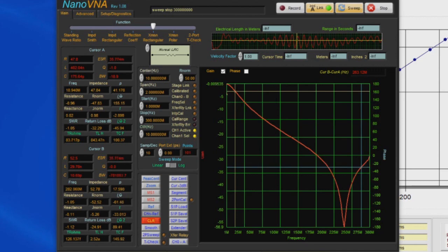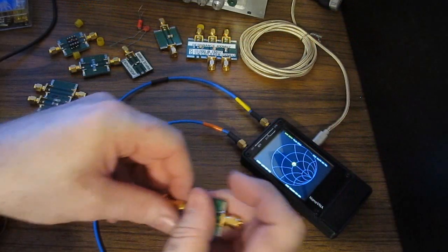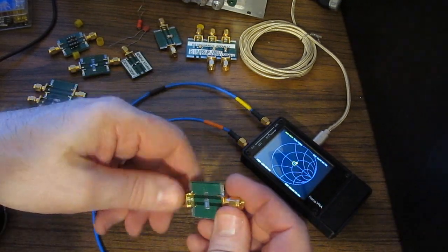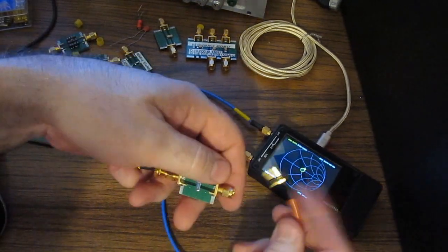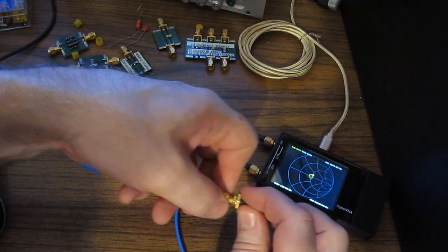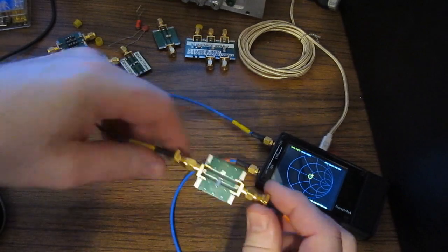38, 33. Again, a fair bit of noise. One thing you could probably do is zoom in on the area that you're trying to measure. Again, you may end up having to add some ferrite to the cables, or just getting a common mode choke. You might also end up having to add some attenuators to try to help with the match.